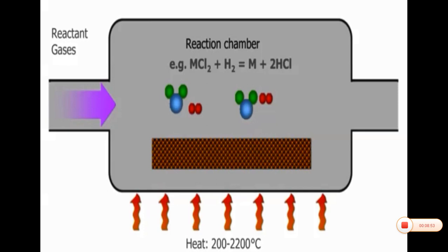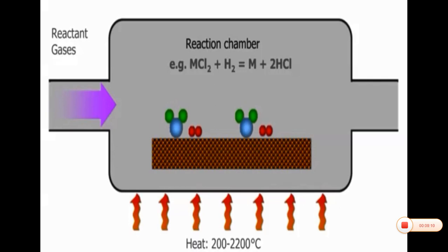We adjust the process conditions such that the mixture does not react until it comes in contact with the solid surface of the substrate. When it comes in contact with the solid surface of the substrate, the gases are adsorbed on the surface. They are held on the surface by weak localized attraction. The adsorption allows the two gas molecules to react together and create hydrogen chloride waste gas.